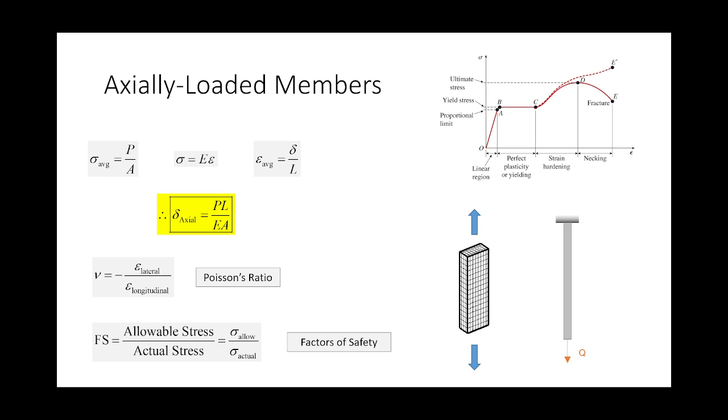Finally, and I hope by now that you understand the concept of a factor of safety, that there is a difference between the allowable stress and how much we're actually applying. This is arguably much simpler than what we do in steel design with LRFD or anything like that. What we're talking about is basic. The allowable stress is 50 KSI, but if I use a factor of safety of 2, I'm going to restrict that stress to 25 KSI. Just cut the allowable stress by the factor of whatever your factor of safety is.